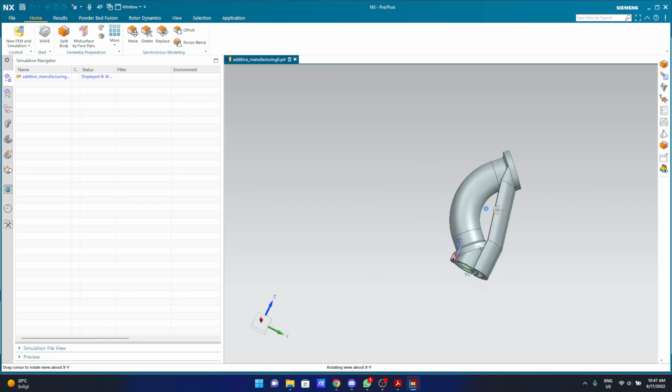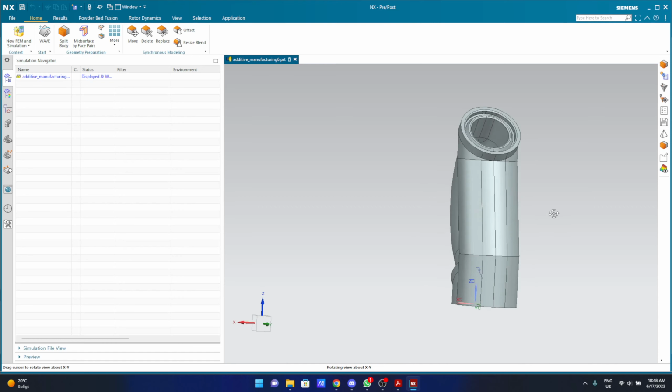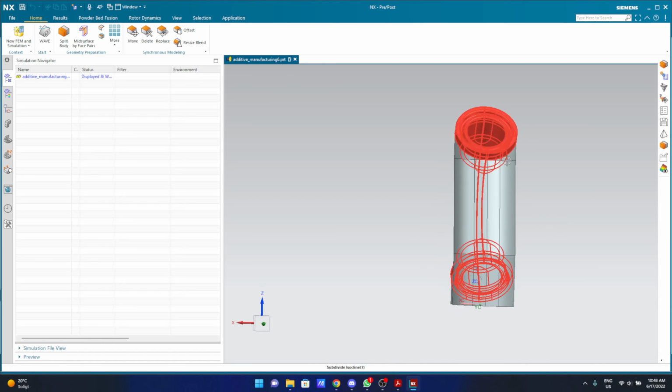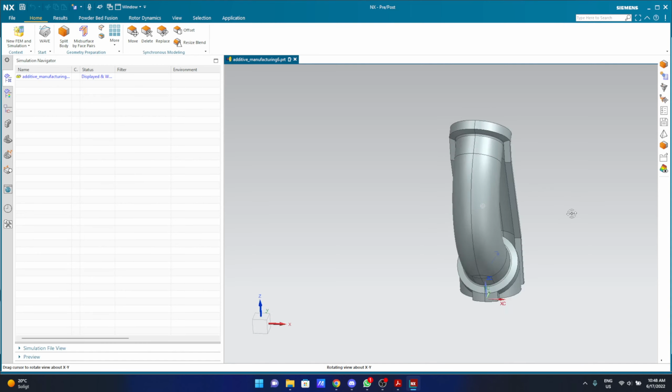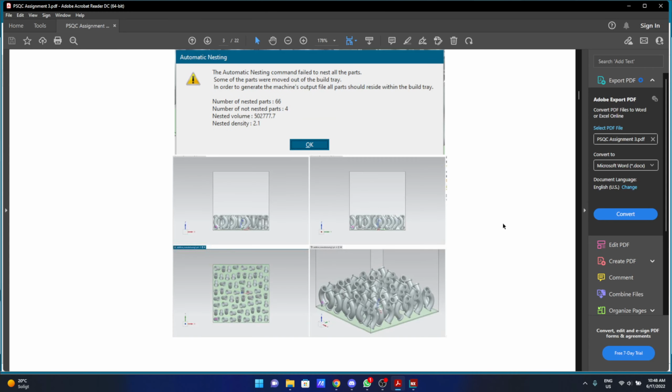The third reason is the supports. If you can see, the supports are symmetric as well. So when you remove them, it will put the same stresses on both sides. So again, the part will stay symmetric. This is the reason why we go with this orientation. I mean, I go with this orientation. You can explain it on your own.